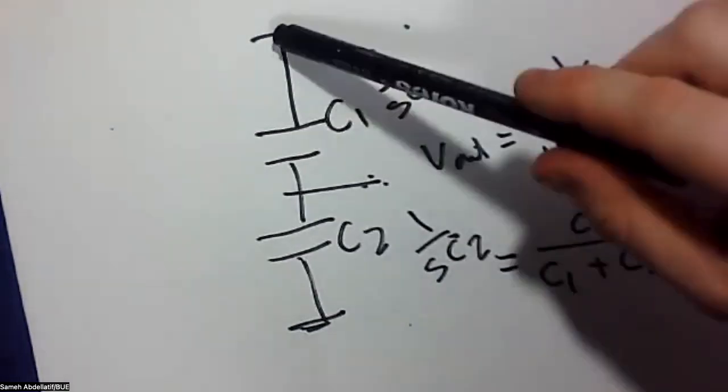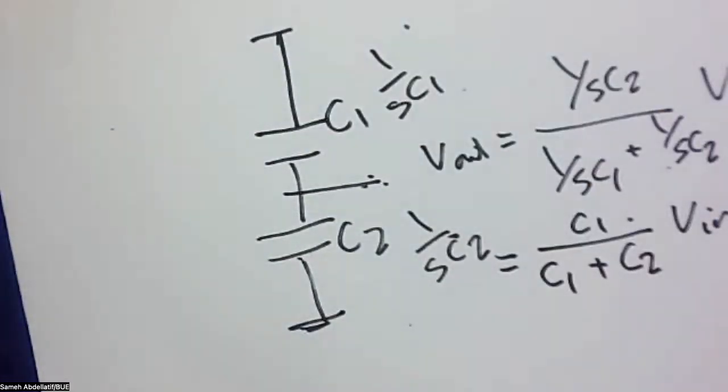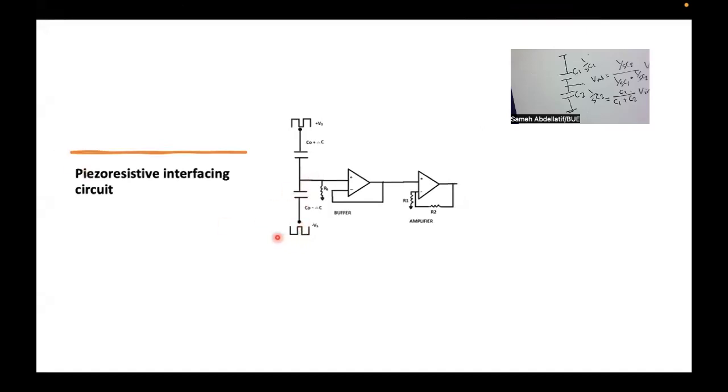That means that your V input, the voltage applied between these two terminals, should typically be some sort of an AC signal. That's why if you return to the slides, you will find that we use some sort of a square wave signal or a pulse signal to feed these two branches, so that they can have a capacitance effect. And here the effect of the frequency is diluted because you are using a ratio between C1 and C2. That's why the s impact is not in, but still it should not be equal to 0 to avoid an open circuit behavior. So this is a first important comment.